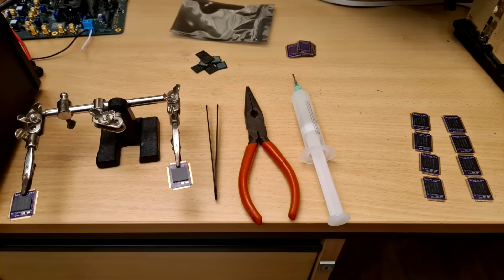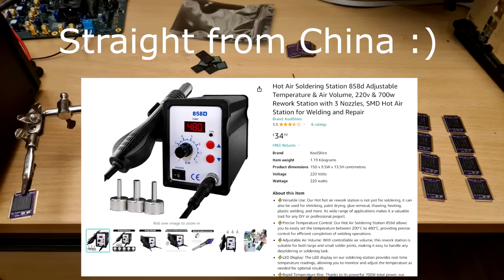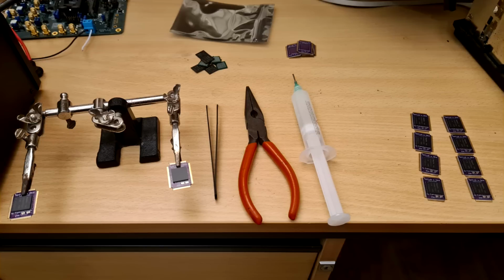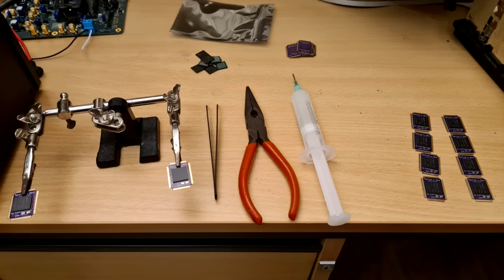Then what I started doing was checking that I can manufacture these more rapidly. So this is my kind of setup here. I can solder 2 devices at once. What I did was I upgraded from that heat gun. Now I have a proper hot air station, so I can control the temperature most critically. I use this tacky liquid flux. This sticks to the PCB quite nicely. It doesn't get messy. It actually really contains itself under the BGA, which is really nice. This is only a 2-step process, so first I solder on the BGA, and then secondly I have to add the solder bridges on top of these pads. All in all, it takes about 10 minutes to do 8 parts, so that's for 1 Xbox, and that's a pretty good amount of time.